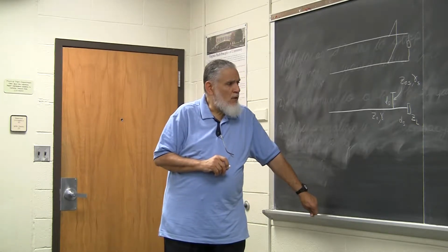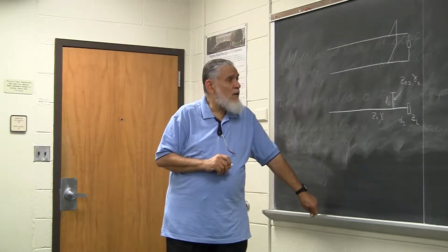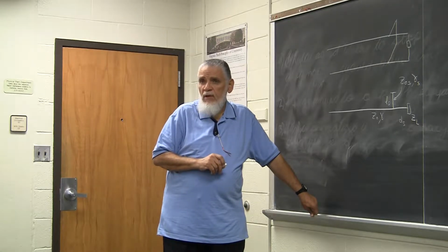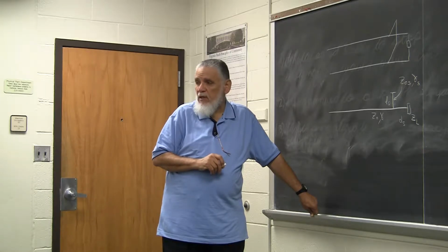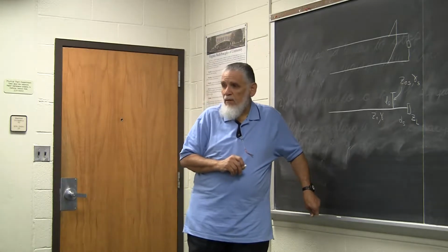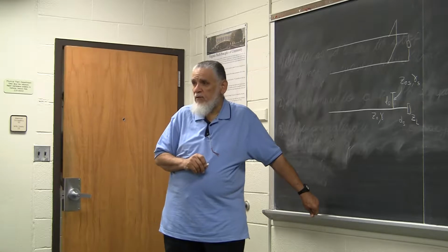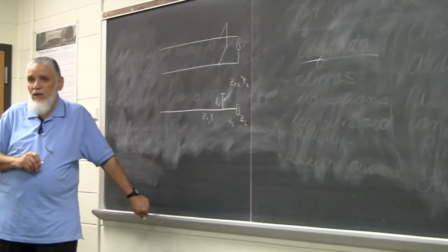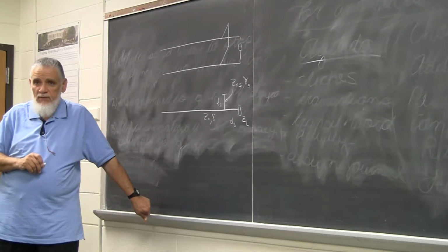The whole idea is that we would like to move away from the load until a location where we match the real part. And after we match the real part, what's left in the matching process is the imaginary part, which can be taken care of using reactance.